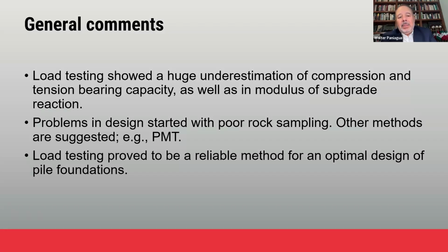My perception is the problems in design started with poor rock sampling. Other methods, especially in the shale, would be using pressuremeter testing and trying to evaluate the bearing capacity through these methods. And well, finally, load testing proved to be a reliable method for an optimal design for foundations, but you should be aware that the amount of money spent on testing should be a little bit, and the amount of savings should be a lot.